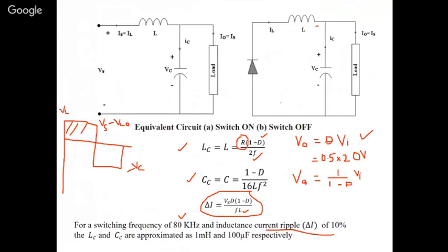Okay, boost converter. So that's why we say in a boost converter it is not a linear characteristic. It is a little difficult for an MPPT. Mainly, students don't go for boost or buck-boost. The problem is there is a non-linearity, so it is a little difficult. You have to be very careful about the change in duty cycle.